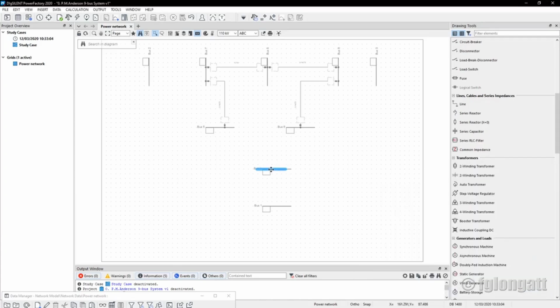You select the bus bar. Selecting the bus bar, you can move it wherever you want with a click. But if you want to extend it, what you need to do is click at the very end, then release at the location that you want, and now we have a bus bar that is a bit longer, okay? Now the bus bar is similar to the bus bar in the single line diagram.